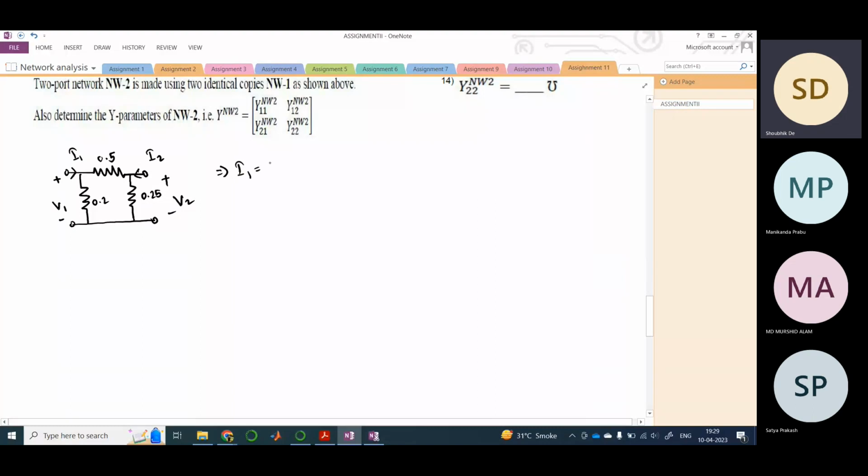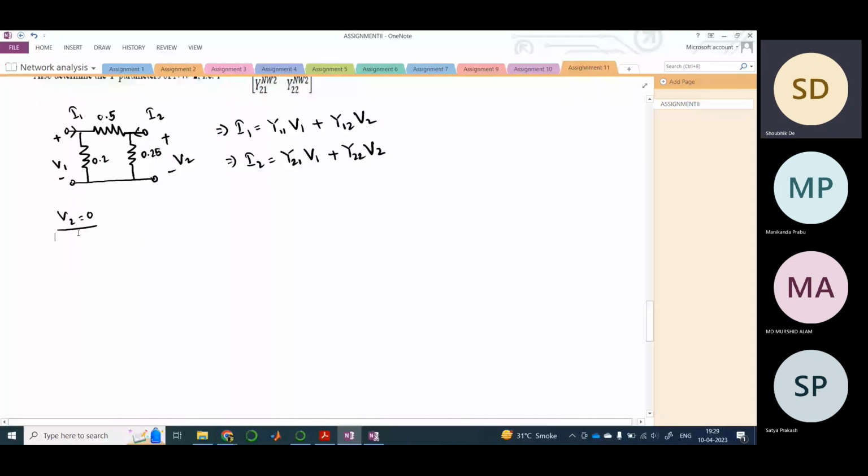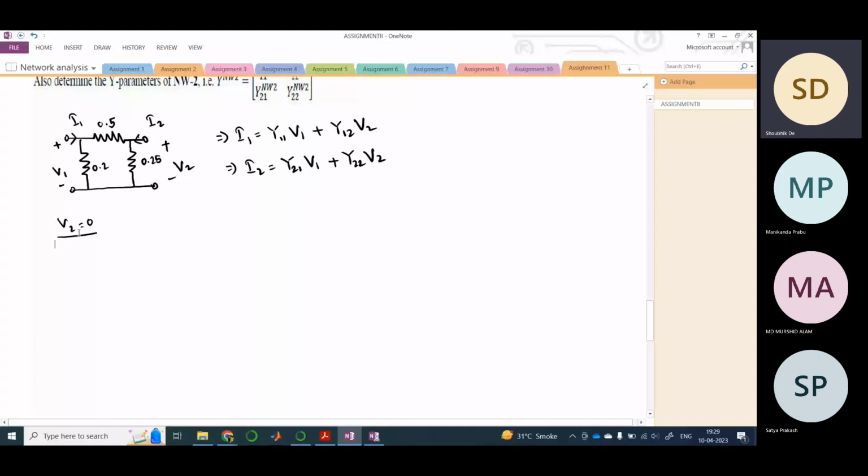Right. So what is our y parameter? It's nothing but I1 equals Y11. It's admittance, inverse of resistance. That is why it's Y. So as a result, we need to first put V2 or V1, whatever you may want to use. First we will short the terminal 2, right? V2 equals to 0, because an open circuit would mean current is infinity.